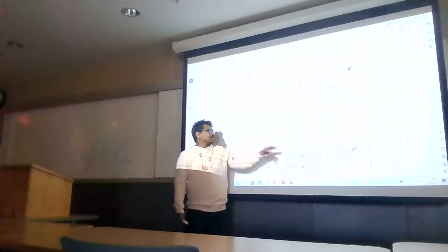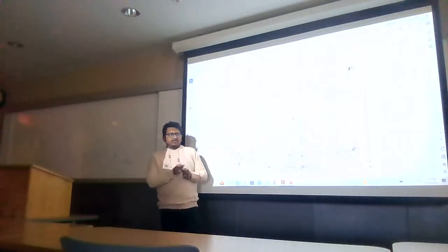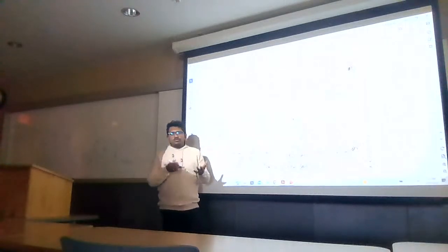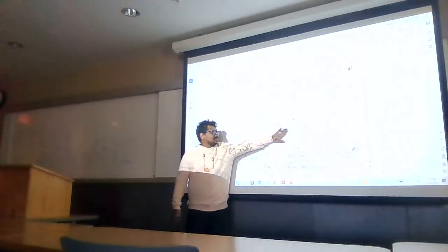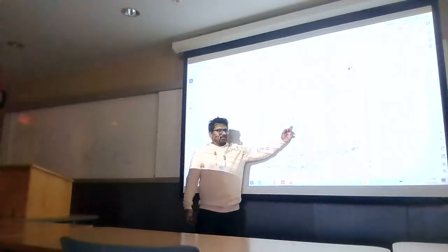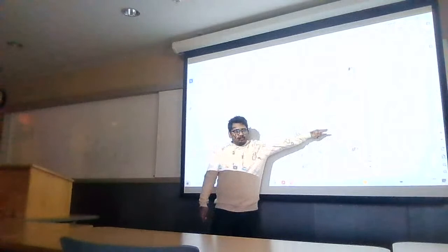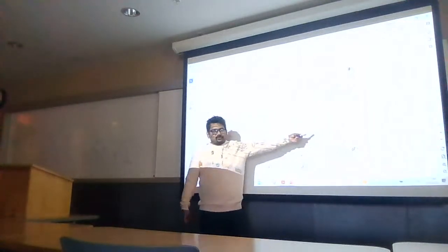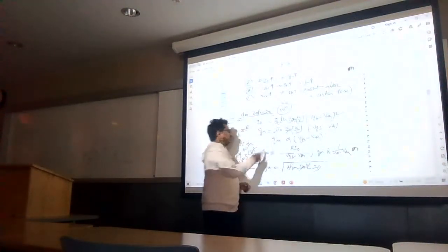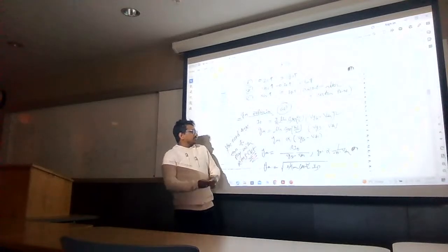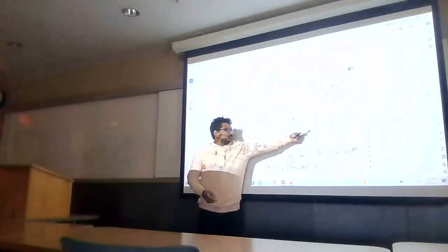Okay, basically, this mu n and Cox are technology-dependent parameters. They depend on which process is used to fabricate the chip, so this is not in our hand. You can say this is constant. We can only change the width and length of a transistor. The threshold voltage is also constant. We cannot do anything with that, but we can play with the VGS. So these are the things I can play with for GM. If I assume the rest is constant, then you can see my GM is proportional to this value.